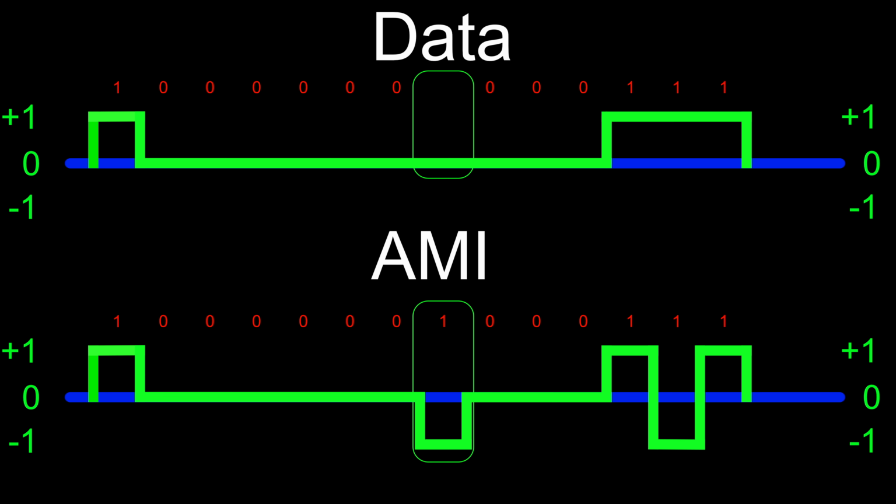This was done because if you try to use the same polarity or direction of change, then the baseline can slowly creep upwards depending on many factors, and eventually it may raise to the point that the detection equipment can no longer tell the difference between a 1 and a 0.